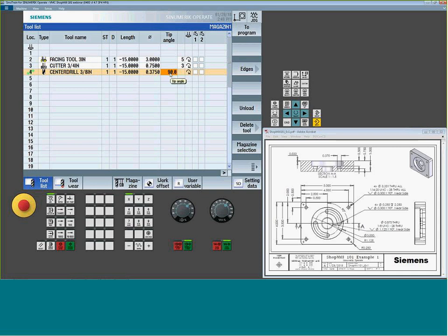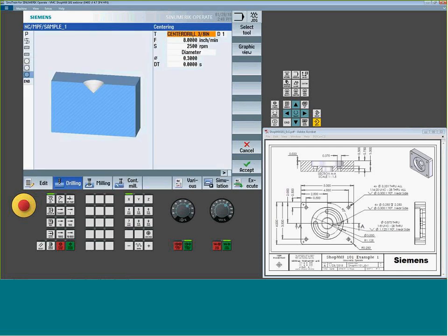So in this case, I'm saying this center drill is a 90 degree. Now, this isn't a combination center drill. This is a true NC style spot drill. If I need my coolant, certainly remember the appropriate spindle rotation. Say to program, plugs in the name, fill out speeds and feeds. Now, when you get to drilling, it's not feed per tooth, but it's feed per rev, like you would typically know right out of your tooling catalog. And it's still surface footage or straight RPM. So either scenario you can use.